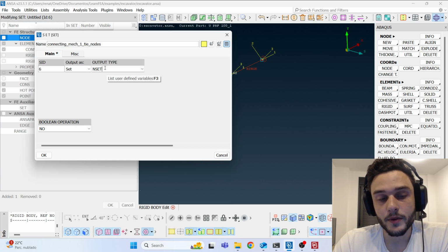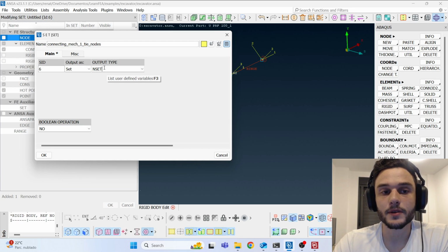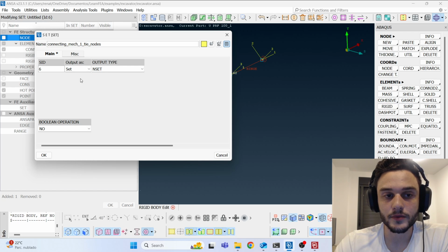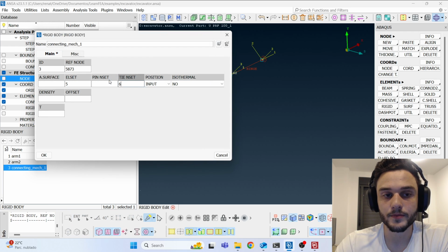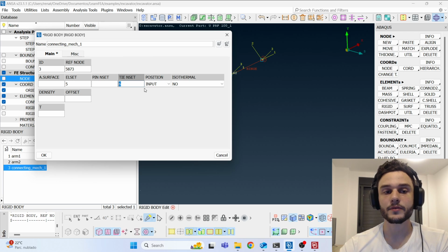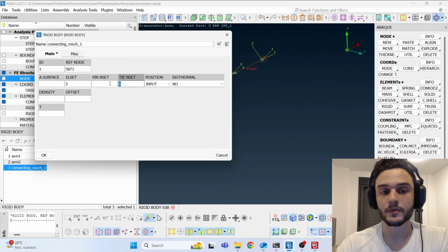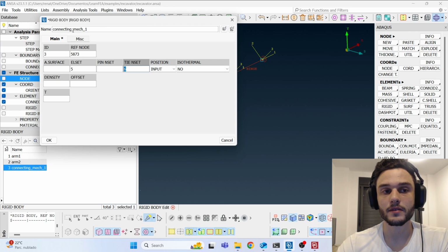But I like to define it most of the time. Click on OK, and then double click on this new set that we just created, and you see that now we have the ID of this set here in this rigid body. Click on OK.